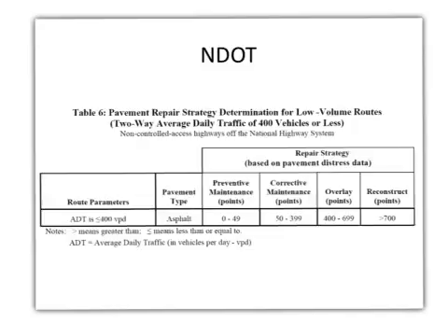If the pavement condition number is somewhere between 50 and 399, then we have to have corrective maintenance. And then if the numbers keep increasing, from 400 to 700, this is an overlay. And if the number of accumulated distresses over time is more than 700 points, then we have to do a reconstruction. The number that Nevada DOT uses goes up to about 1700 points. So we keep lump summing all the numbers until we see how bad the road is. So it's different than PCI.